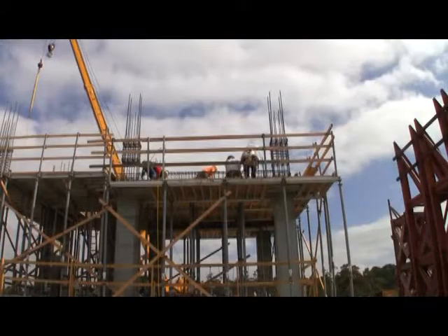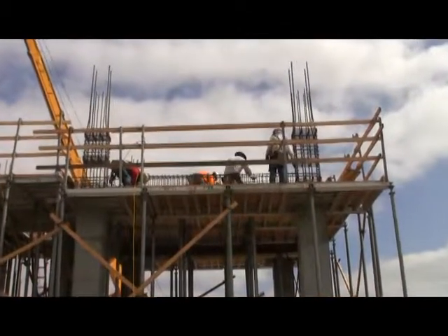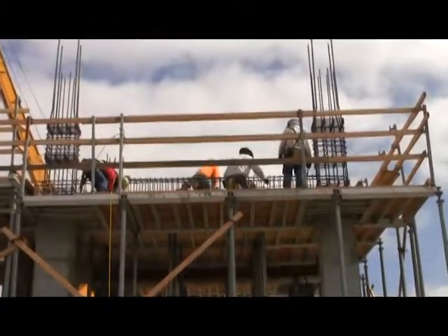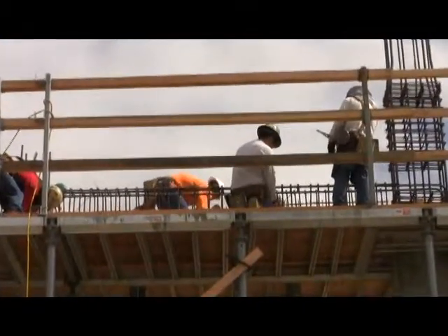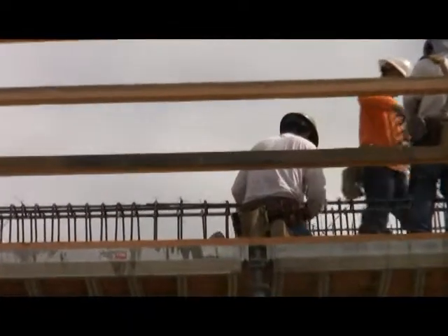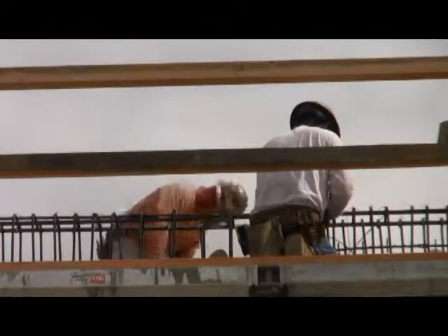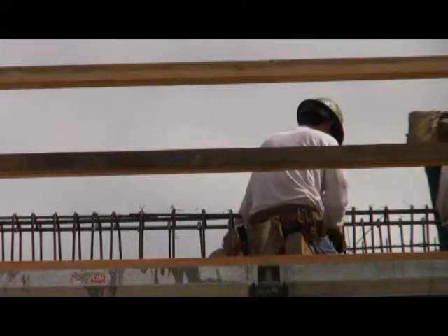After the concrete in the columns and shear walls on the first floor were cast and cured to sufficient strength, the construction of the second floor began. First, the necessary formwork was installed, and then reinforcement for the second floor beams and floor slab were placed. Concrete beams and floors, just like columns, need to be reinforced in both transverse and longitudinal directions.